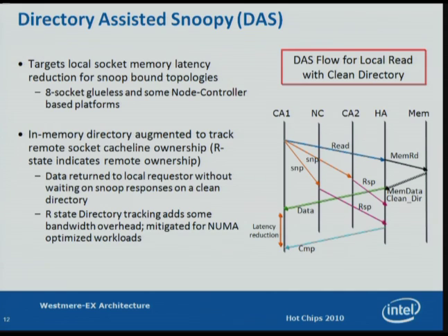So that you return data early, and then you wait for all the snoops to resolve, and then send out the complete. So what used to be data return coincident with the complete, essentially the data is returned early, and you save latency in these configurations. This is also useful when we scale up with node controllers where the latency might be snoop bound.